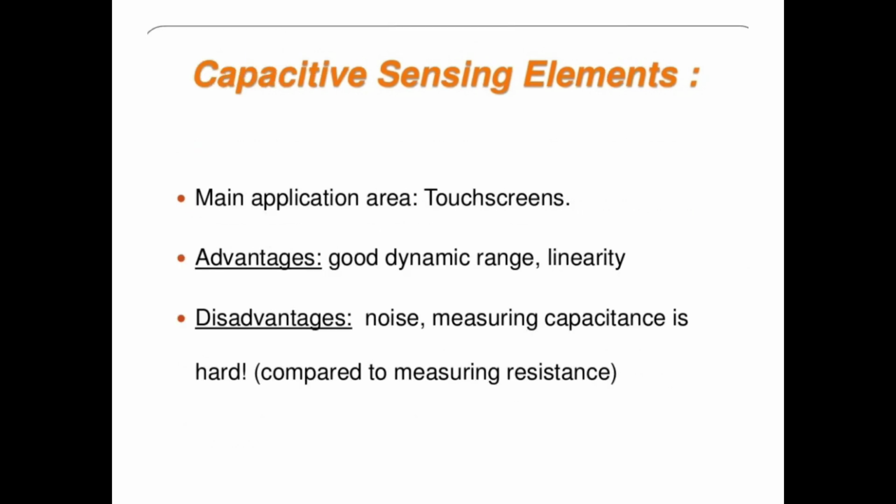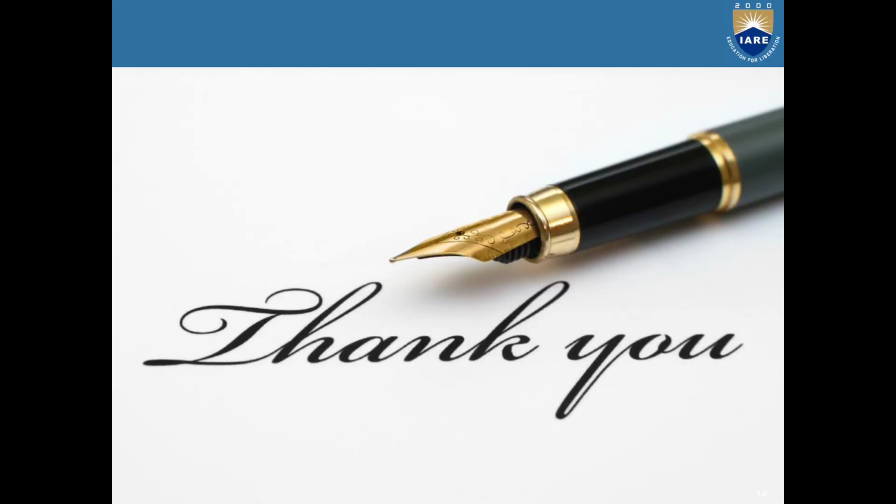Capacitive sensing elements. The main application area is touch screens. Advantages are dynamic range and linearity, and disadvantages are noise, and measuring capacitance is hard as compared to the resistive.